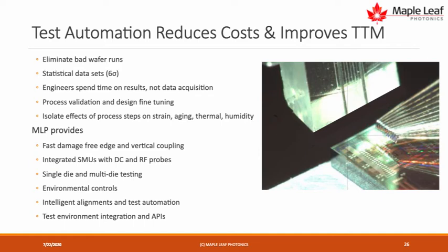So having test equipment that has the ability to monitor either an on-chip photodiode or perhaps an external photocurrent, an external power meter, to be able to tune up ring resonators or Mach-Zehnders, either for peak or for null, and thus configure the internal state of this complex circuit so that you sequentially go down a line, sequentially illuminating the parts of the circuit that you want to test. And so having a test system that understands that and then intelligently configures the chip is a very important part of success.